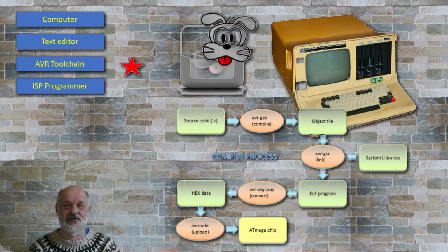Then you are going to need a linker, and finally a program loader. It's a program that communicates with the target platform, in this case your printed circuit board, and specifically the microcontroller in that board. So it's uploading your code into the microcontroller.